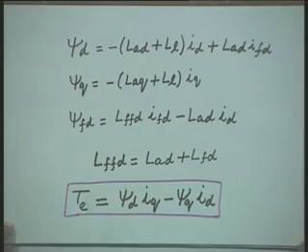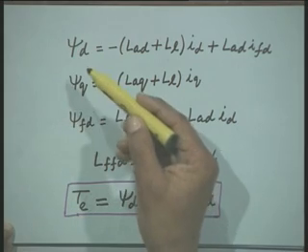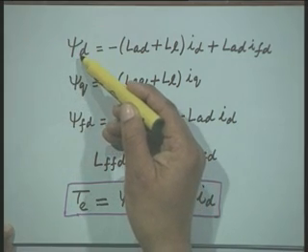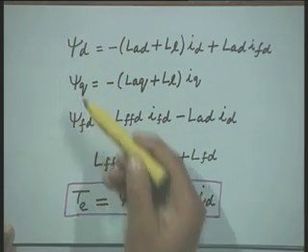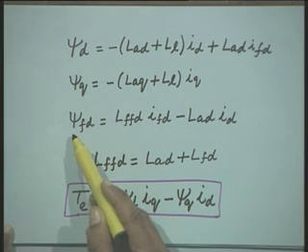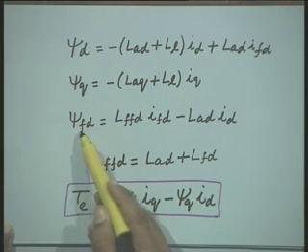Therefore, we will be in a position to write down the network equation, and we will be in a position to write down the synchronous machine equations, and since these two components are connected, we will be in a position to correlate them. That is, we will find the network constraint equation. Now, these are the 3 basic equations which represent the d axis flux linkage, the q axis flux linkage, and the field winding flux linkage psi FD.